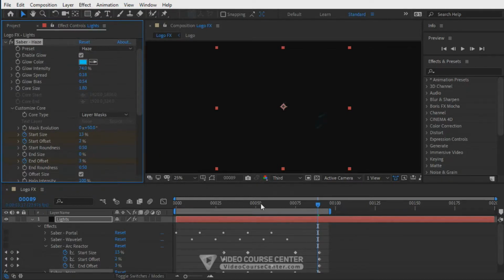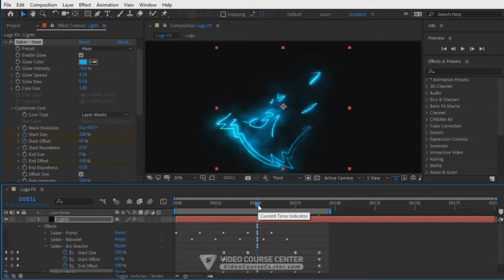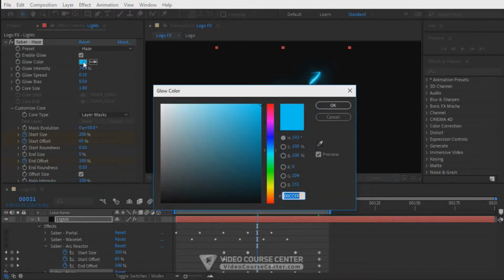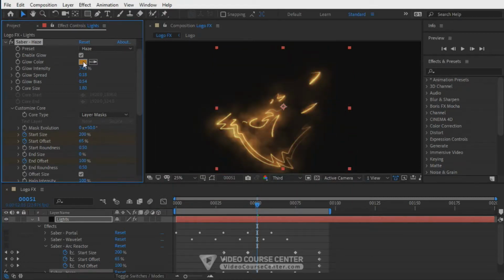B17317, something like a dark orange color. Let's decrease the brightness, so reduce core size a little bit, set it to 0.75. And let's change glow intensity to, for example, 33%. Let's decrease glow spread, so hold Ctrl key and drag over this number to have a shaky line. For example, set it to 0.065. Okay, and change glow bias to 0.07. Okay, check composite settings and alpha mode again. We should have add and disable options. Great. Okay, now again I want to offset our keyframes.